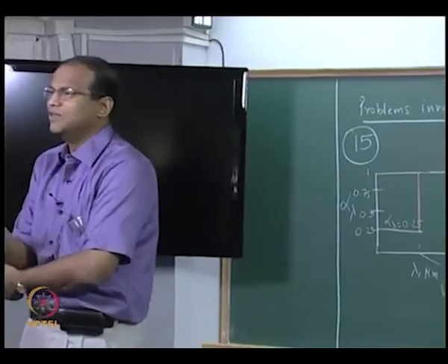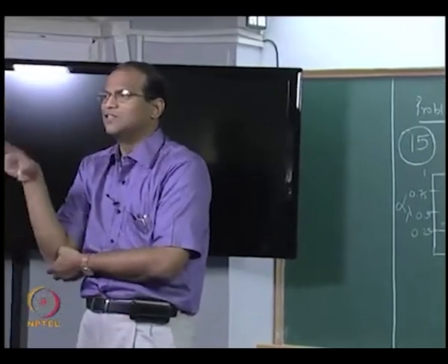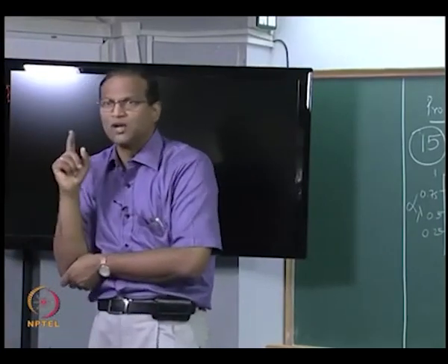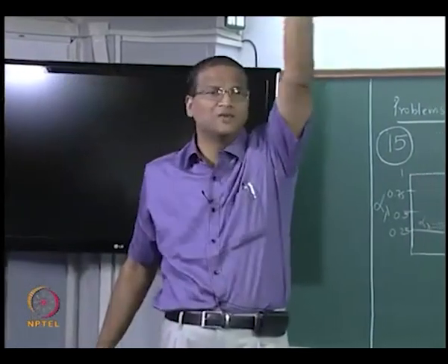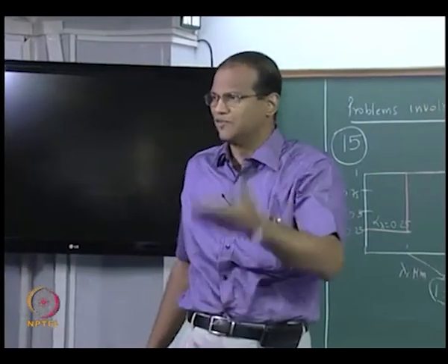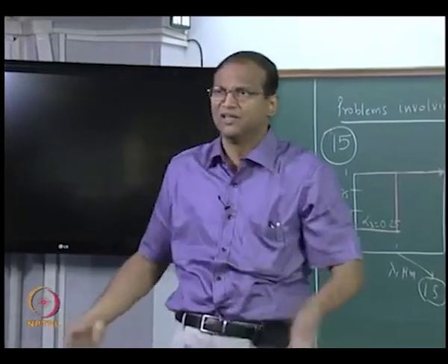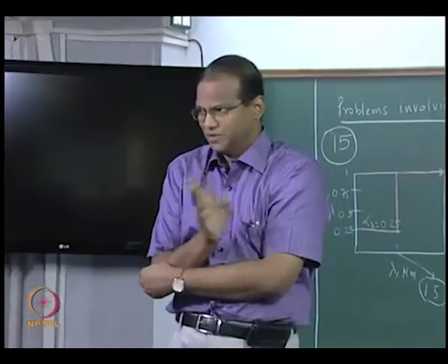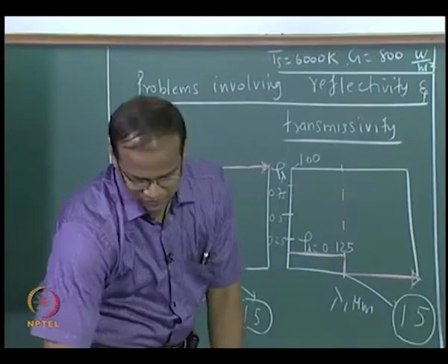Why do you want to get into all this? If I do all this, you will get that 1353. That is the solar constant, but that 1353 is just what is entering outside the earth's atmosphere. Then so many things are happening because of carbon dioxide, water vapor, and so on. Same thing with the transmissivity also. This black body story helps us to use the F function chart and get the properties. Okay, fine.